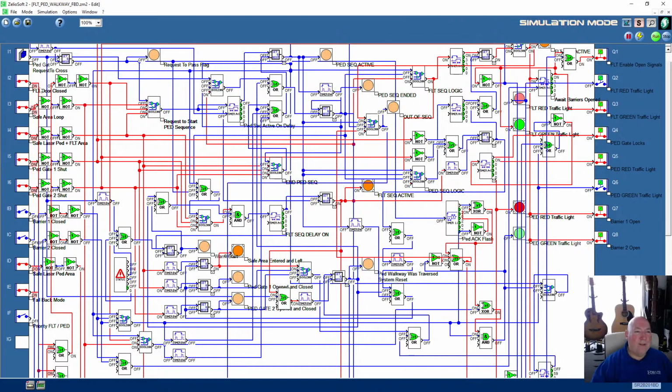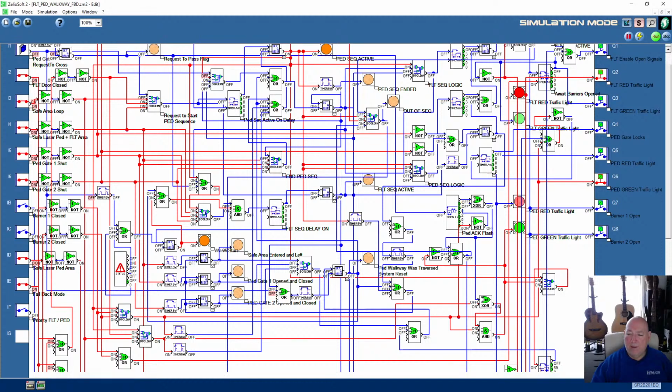So now we request a crossing from a pedestrian. So we requested a crossing. It's changed over. It's transitioned over to FLT mode. Sorry, pedestrian mode. It's counting down the timer. We haven't gone through yet, but at this point we need to indicate that we're being held open. We've got the fallback mode on, so it needs to still flash the reds every 3 seconds. It's not going to be able to do that if we're on green here, so we need to sort that bit out next.